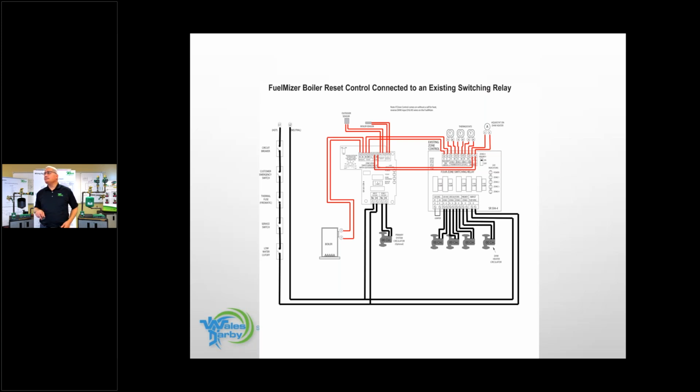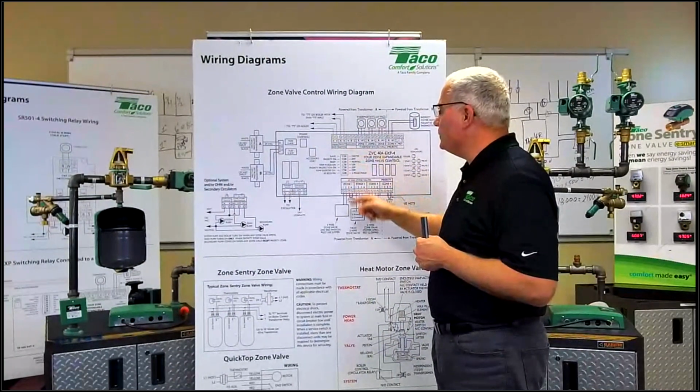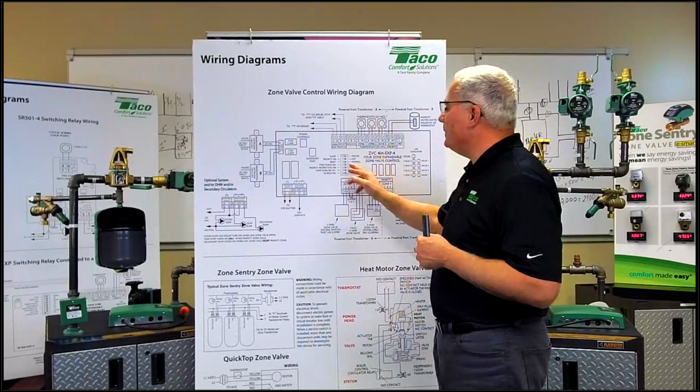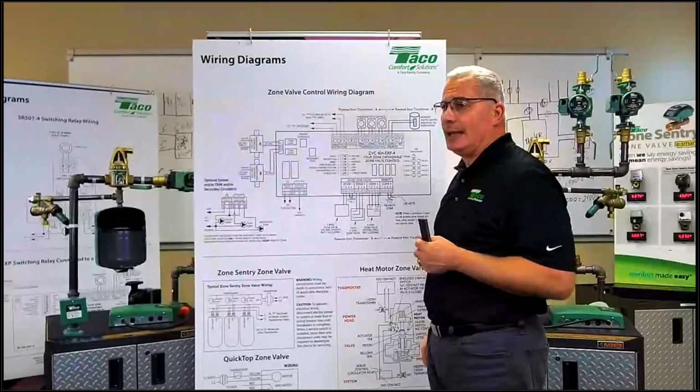All right, yes, sir. Jim, real good question here. Gentleman asked, do you have to cycle power when you're hitting your dip switches? No, you don't. I told him it's always just best practice to power down, make your dip switch changes, then power back up. You can do it live, but just across the board with other products, it's best practice, always safe to do it that way. If I know what I'm going to do beforehand, I could set my dip switches. But if it was powered and we made the change to the dip switches, nothing would happen.